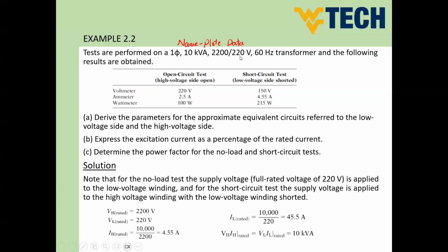So all of the time, guys, we measure from one side and make the test on the other side. So this means in this example, we will have measurements on the secondary side for this test. So all values here are referred to the secondary side. What are these values? Volt and current. Power has no side. So power is power whatever the side. However, this current and this volt are referred to the secondary side.